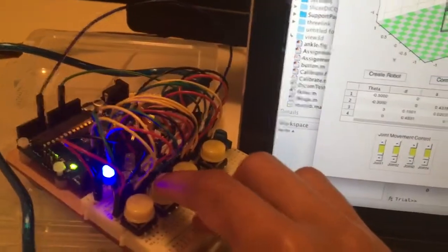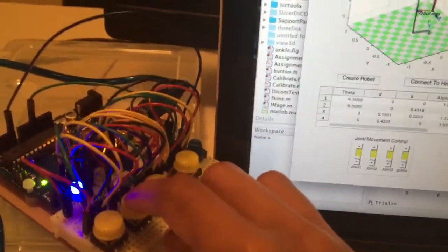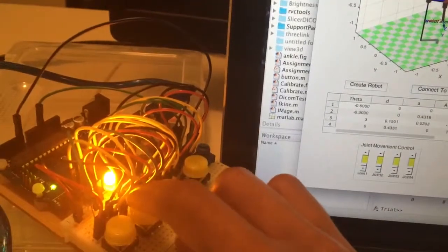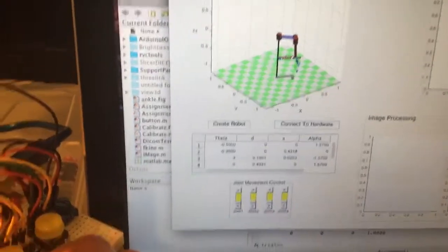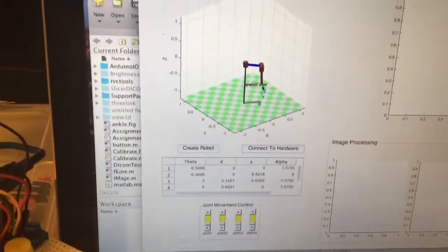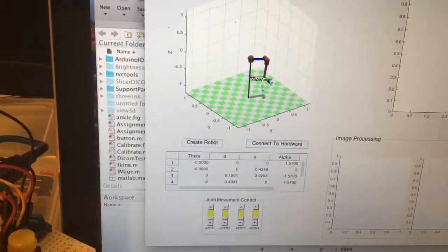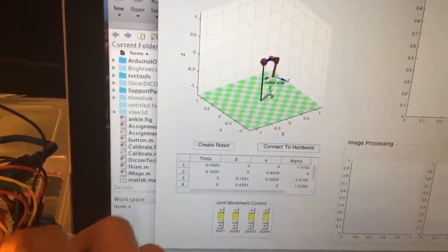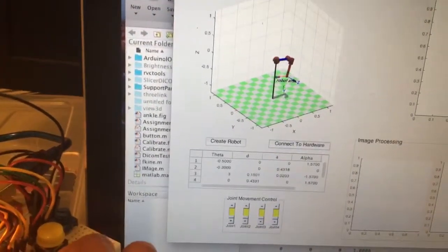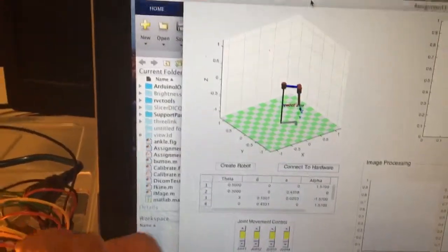And now I'm going to change, I'm moving to Y axis. You can see another light is on, the other will be off. So now Y axis is active. Let's move it Y. It's moving. Now we're going to change it to go to negative direction, and here it is.